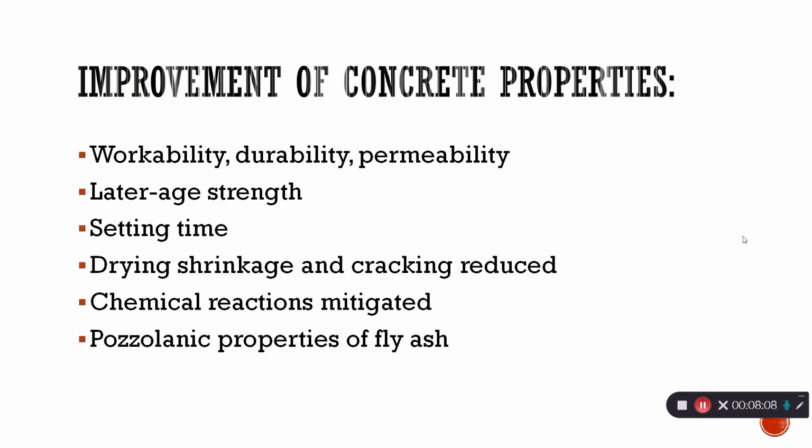When looking at the compressive strengths, the inclusion of 5 to 10% fly ash mixed with the effective microorganism solution significantly increased the strength with curing age. 10% displayed the highest compressive strength for the bioconcrete prepared.